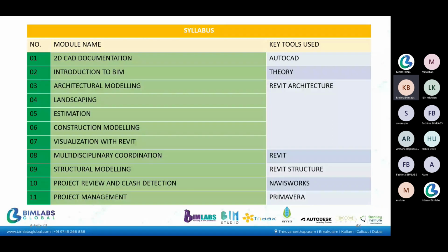So in Primavera, not only planning, we can do the tracking also. That is, after planning, once we are on the real construction site, we can track our project. So each and every day, when one particular activity is done, we can go into our software and update everything. We update whether that particular activity is finished or not, and if it is delayed, everything can be updated, and then we can reschedule.